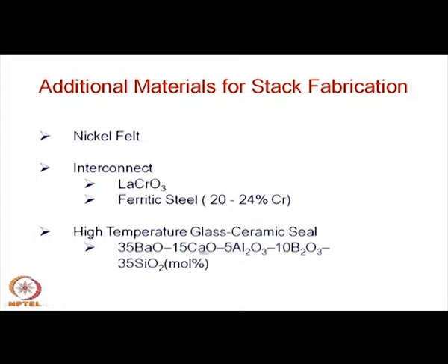So, this is a typical composition, but there are a lot of variations, a lot of different things can be added to this. Sometimes titania or zirconia can also be added, so that they become crystallized, and by crystallizing you change them. So, the crystallization property is important to be controlled, so that one can control the thermal expansion coefficient. We will discuss the interconnect later on in slightly more detail.